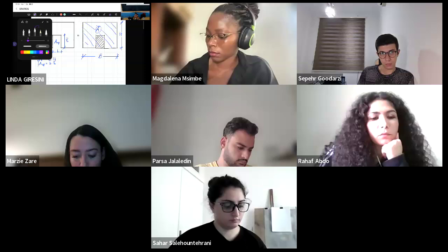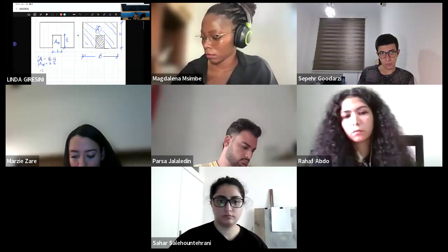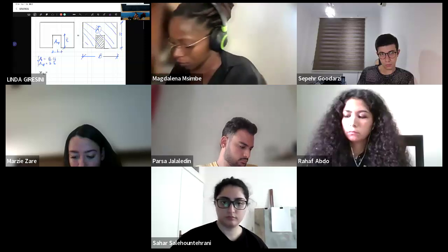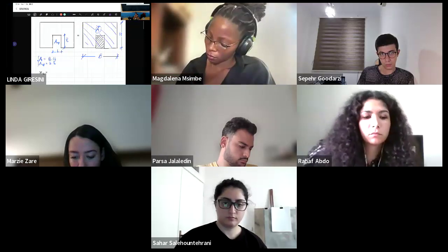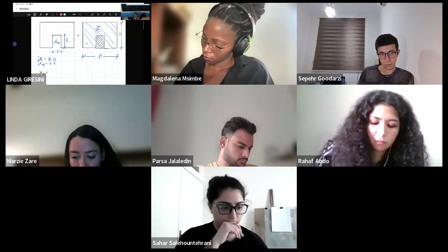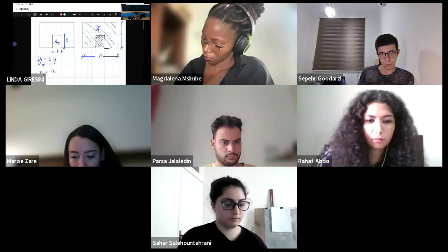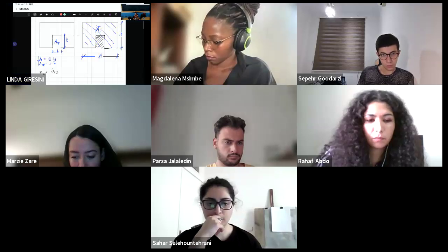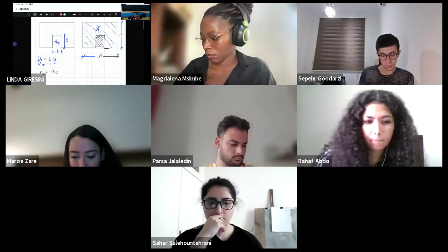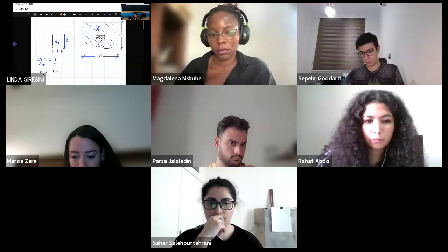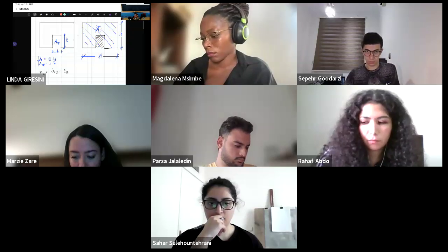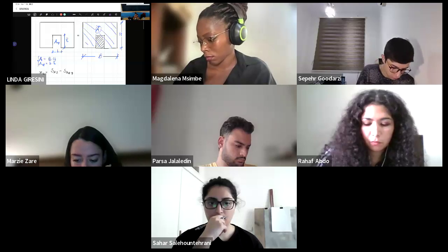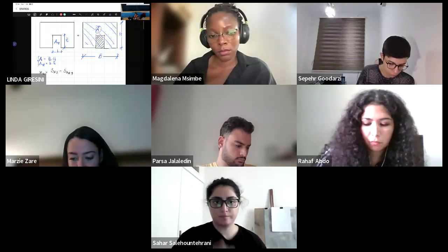Therefore, XC now will be the static moment of the whole area with respect to the Y-axis, minus the static moment of the opening, again with respect to the Y-axis.